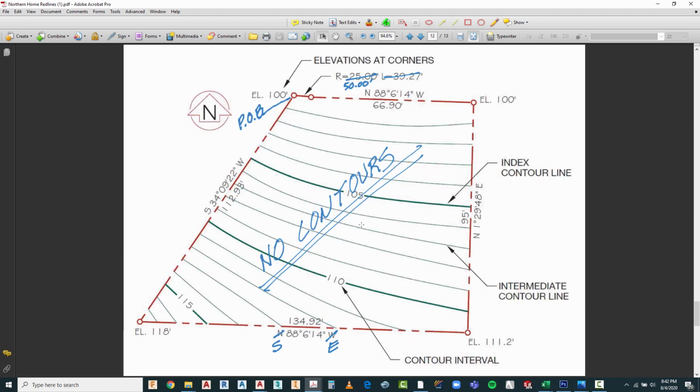turn the property around. Now that's kind of important because what we want is the floor plans to stay exactly where they are. Remember, we've taken great care in aligning them vertically and horizontally so that when they get stacked together in an assembly, they will be in the right location. In addition, typically when you're doing residential, your front door or garage is going to be pointing down or to the right. So we are going to play God, and we're going to be turning the north from pointing straight up typically to pointing straight down.